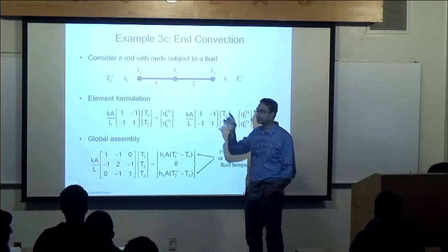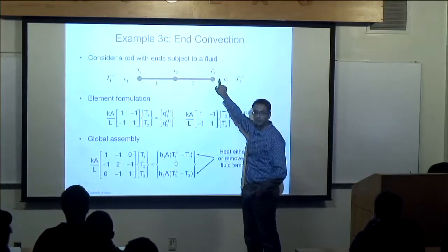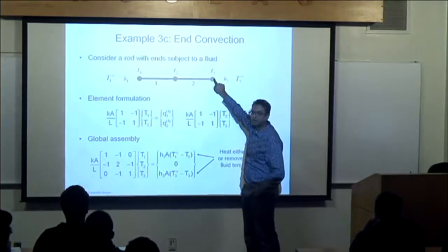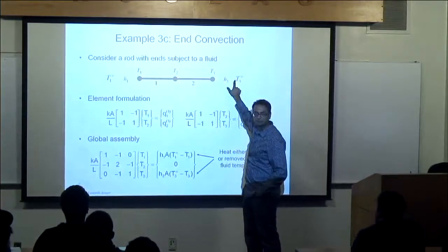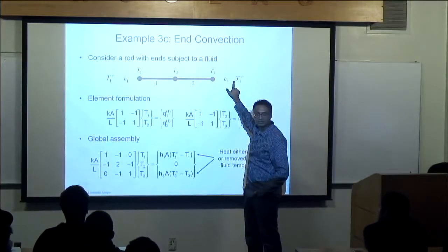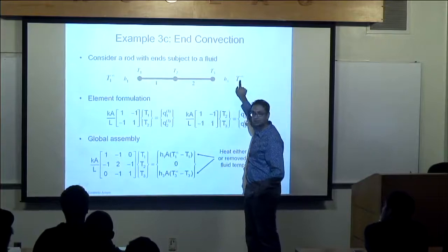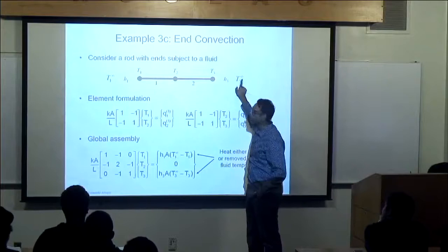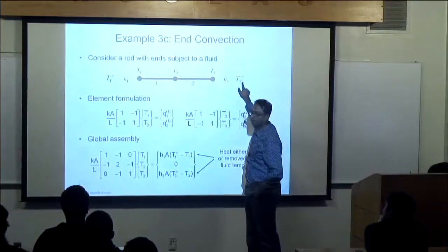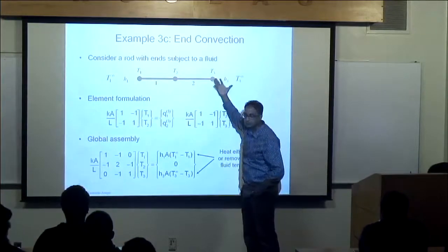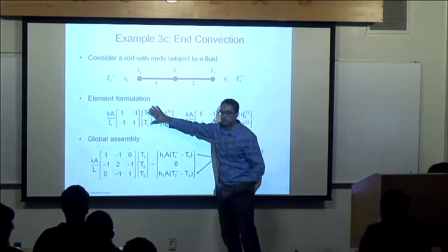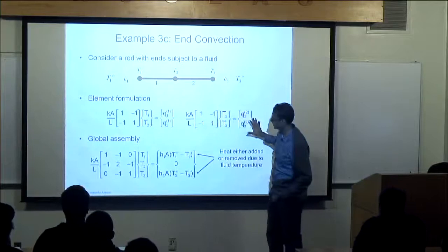Just think of this as a heat flux. You follow me? Isn't that a heat flux? If this node is hot and this is cool, what's happening? I have a heat flux. Is it going in or out? If this is hot and that's cool, which way am I going? Out. I'm losing heat. If this is cool and that's hot, which way am I going? In. Right? Same format, element formulation.